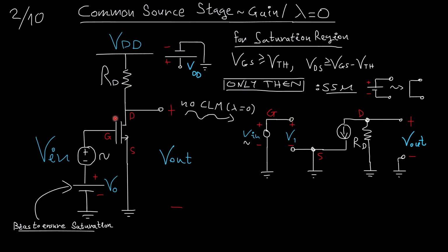The small signal model of the MOSFET device is this, all right, and this is what we call an AC ground. The AC ground is not the actual ground. It's very similar, it works the same way, but it's only in this case where the constant voltages have become 0.